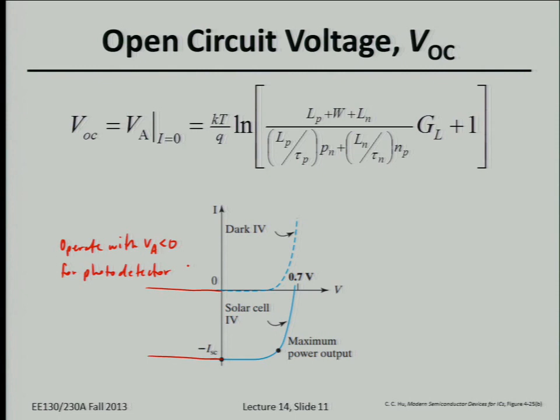If you put a reverse bias on your diode and have a circuit that detects whether or not current flows, you can put a resistor in series with the diode, and if a voltage appears across that resistor, that means current is flowing through the diode. So you can detect a voltage, and there must be some light shining on the PN junction. That's fundamentally how a photodetector works, but we'll cover this in a little more detail later.